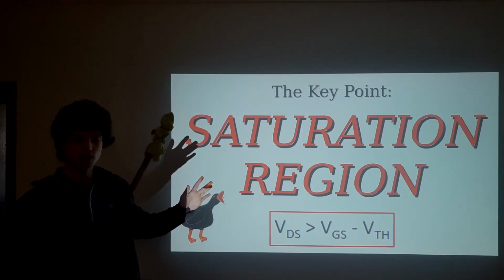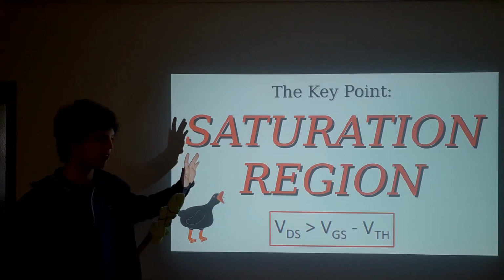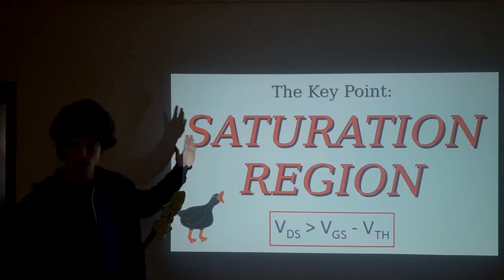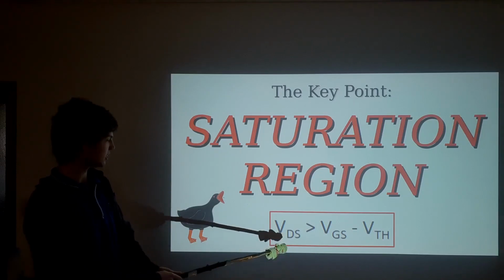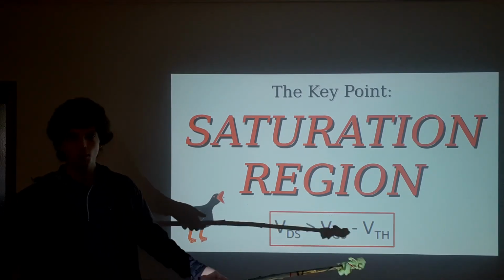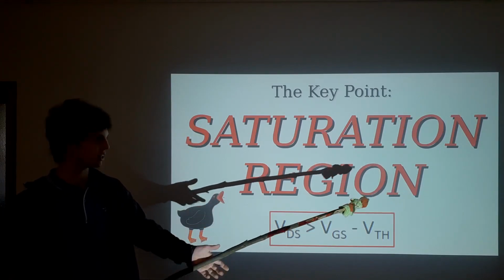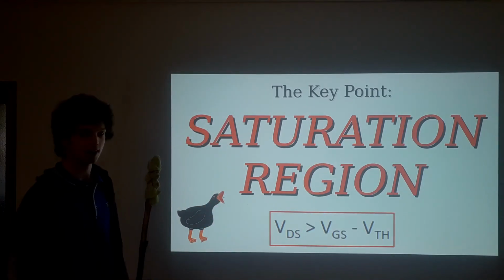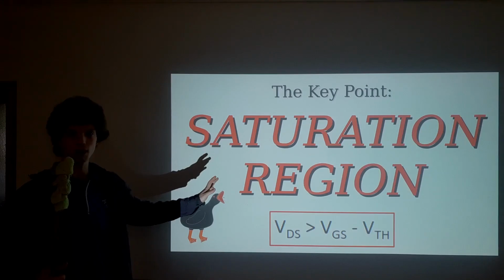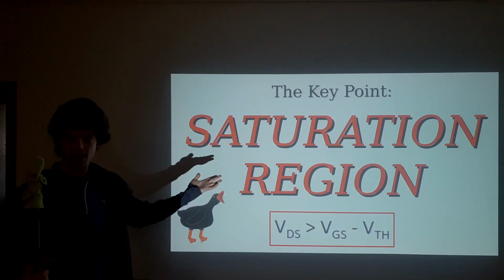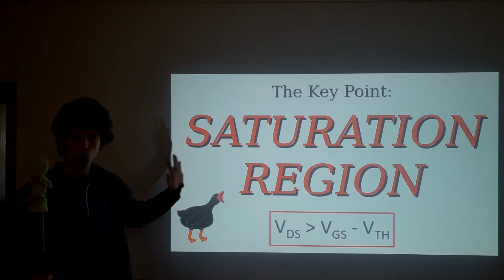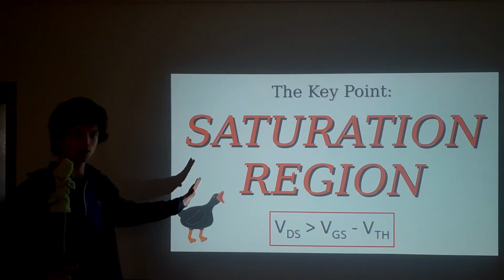But you'll lose marks if you don't, and they might throw us a curveball where it isn't, but practically speaking, it jolly well should be. This is the condition for saturation region. We do a whole lot with this biasing for the sole point of making sure that it's in saturation region. Right, that's the takeaway. So long as you know how to get a MOSFET in saturation region and what it does once it's there, you can wield these things.